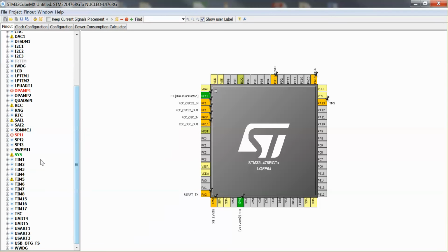and basically the STM32 has a bunch of timers, and depending also on the family and the exact MCU that you're using, they have different functionality. Okay, they're extremely powerful, and they allow you to generate PWM signals. They allow you to use them as counters. They can be used to interface encoders like quadrature encoders with direction and all this kind of stuff.